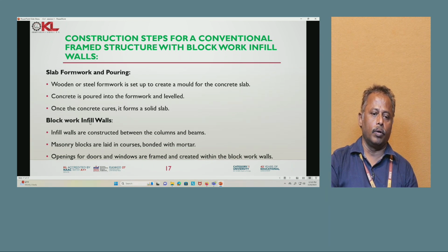Next, blockwork infill walls. The infill walls are constructed between the columns and beams. The masonry blocks are laid in courses and bonded with mortar. The openings for doors and windows are framed and created within the blockwork walls.